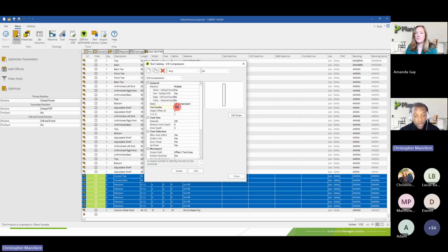The tool number will depend on whether your machine needs a tool number or not. Usually there are 2 big families of machines: those using the tool numbers to identify the tool to be used, or those using the tool name to find the tool in the tool magazine. So that depends on what you use. If you're unsure, reach out to your CNC tech, or even your CNC operator might know the answer. So if it's tool number, make sure you properly set those tool numbers.